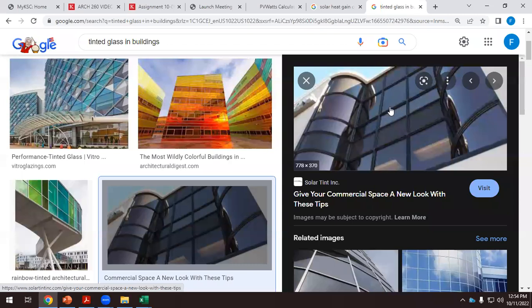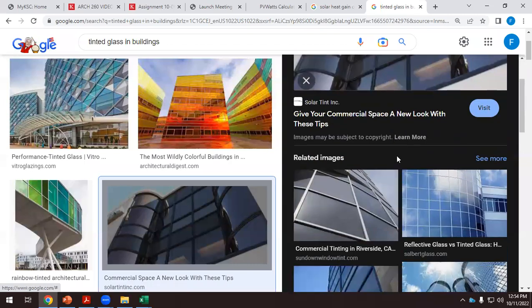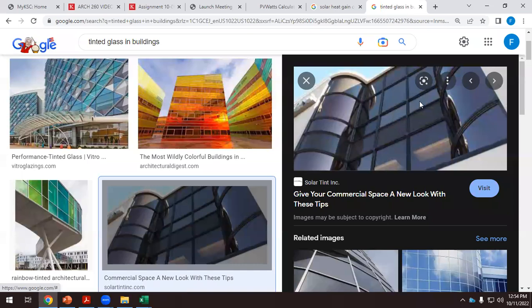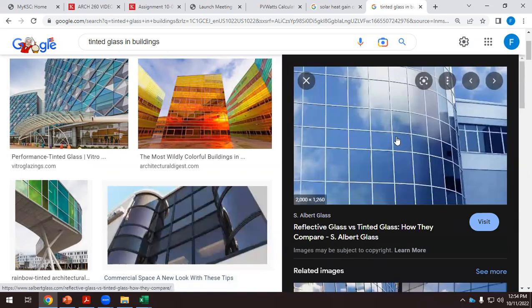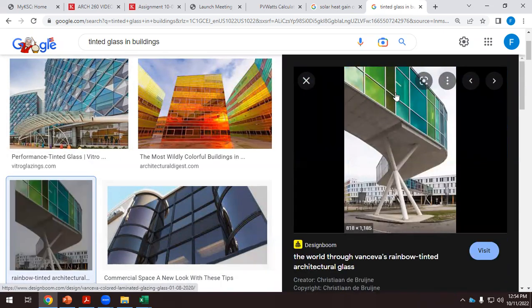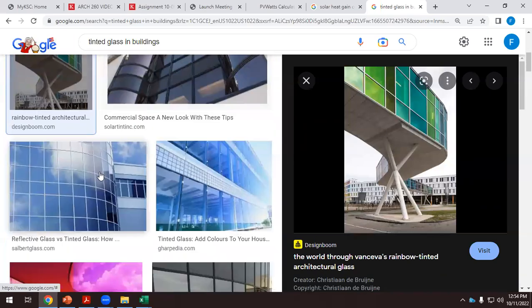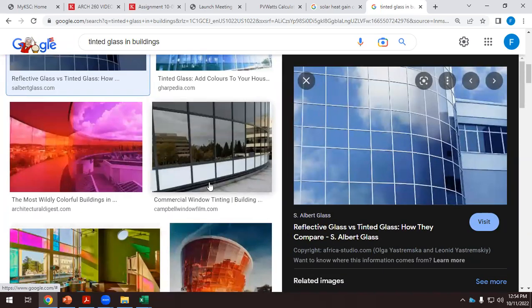Okay, so if we see especially office buildings with a huge glass area, and they're almost very dark gray, that means that the solar heat gain coefficient is very low because basically the glass is not transparent. Sometimes we have this mirror effect. If it's a mirror, that means that it's reflecting a lot of light, and that light that reflects doesn't get into the building.